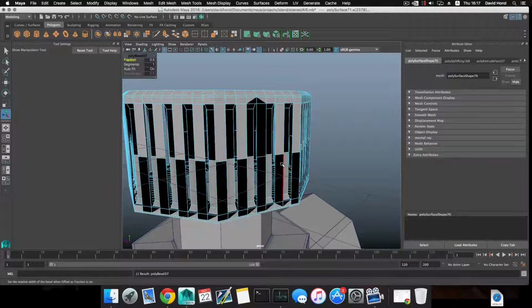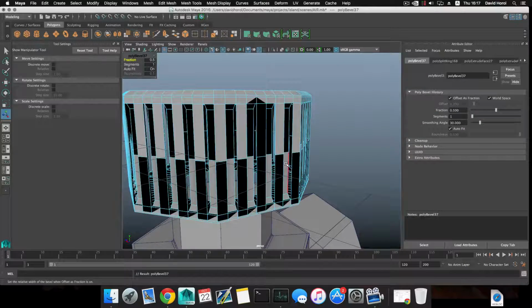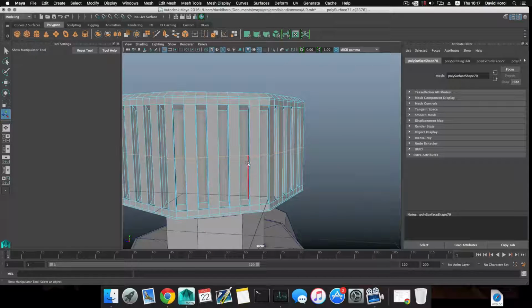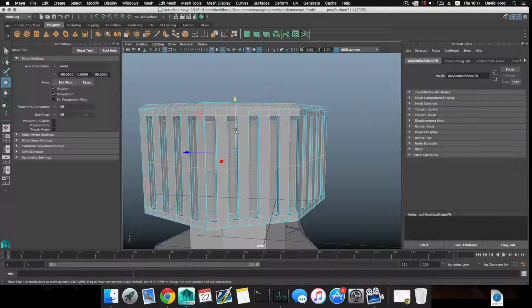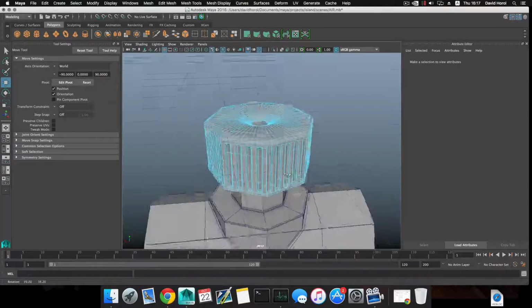I'm gonna add this middle one. Oops. Click on it. Shift right click, bevel edge. For some reason, Maya got into a sort of bug. I can't really do anything about it, well, I can work around that by just adding 2 edges. Press 3, and we will have this.